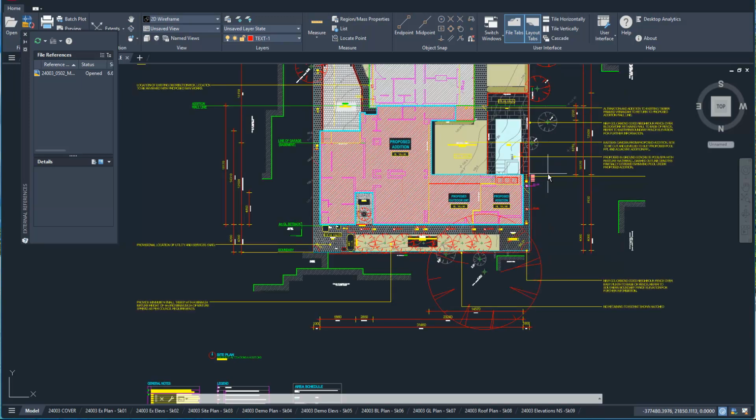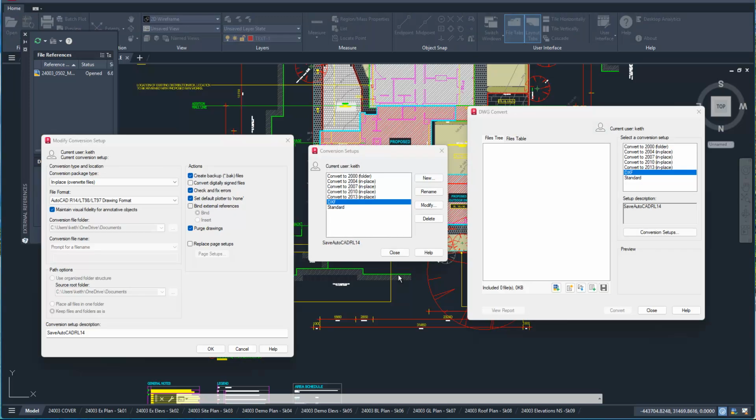And as long as it's got the dimensions on it, we can check that the conversion has gone across reasonably easily. So my next step is to convert this whole drawing into a version of the DWG from Autodesk that is not as complex as this one. I'm trying to get a simpler version so I can move that into other conversion tools. I want to save it as a DXF file, and TrueView doesn't allow that.